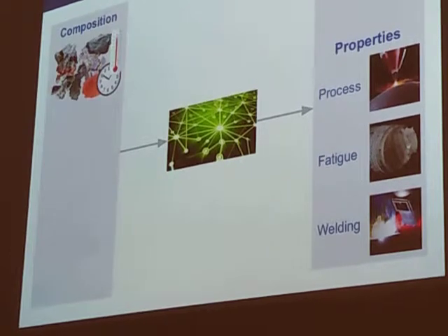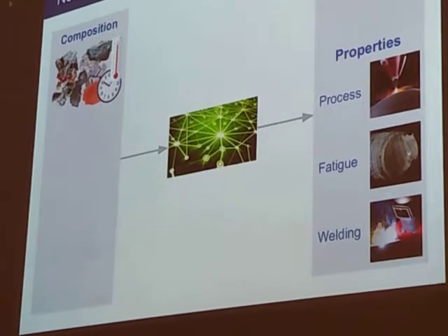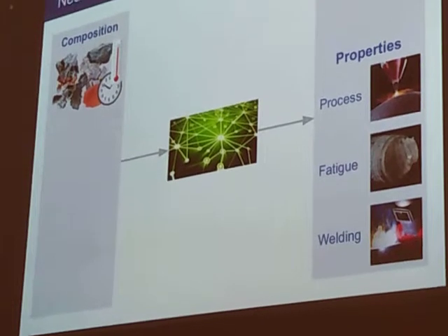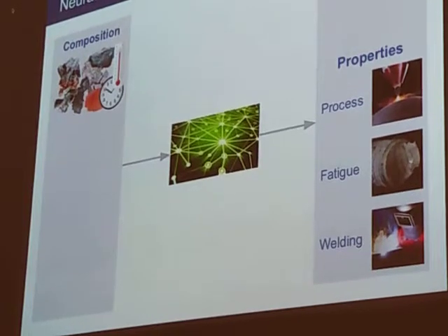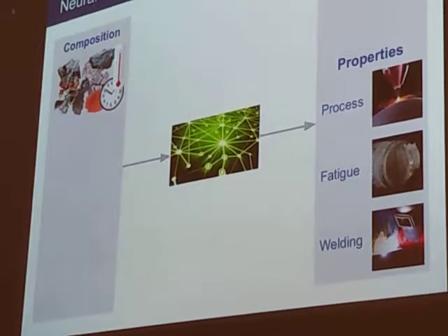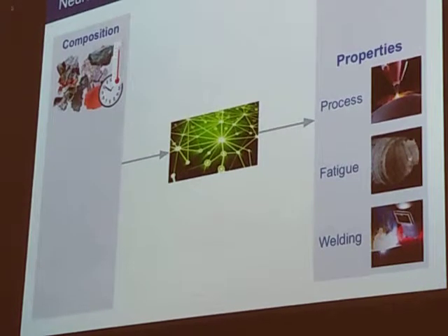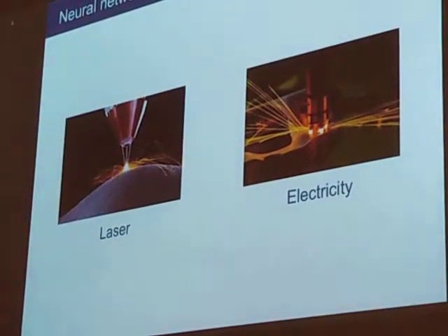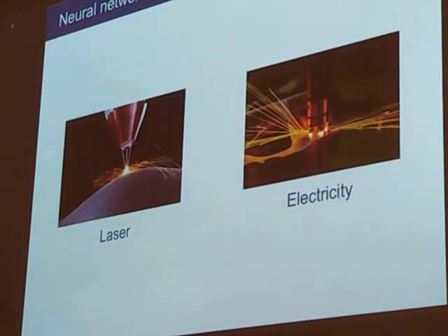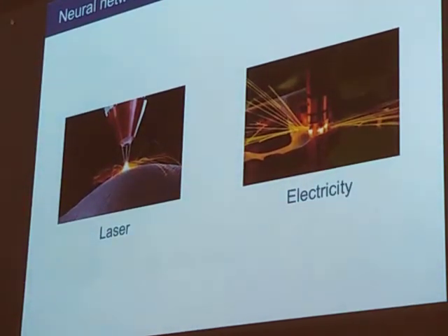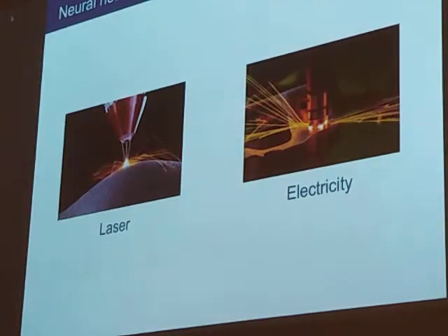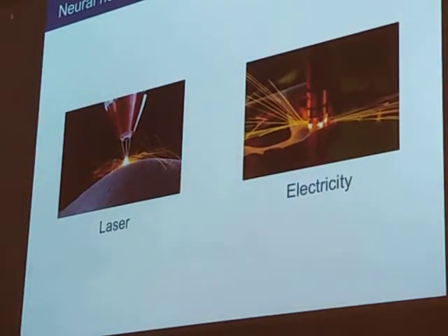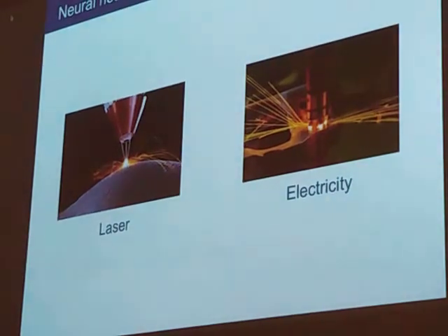Now this is the point at which we're going to have to be inspired and think about how the traditional material scientists would operate. In that case, they would go, this process of 3D printing for alloys of direct laser deposition is analogous to another materials processing technique, that of welding. For in direct laser deposition, we are melting the material locally with a laser beam and pushing it through several thermal cycles, whereas in welding, we could be melting the material locally in space with electricity and also pushing it through several thermal cycles.